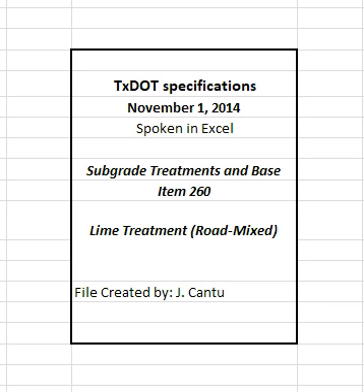2.2 Subgrade. The engineer will determine the sulfate content of the existing subgrade in accordance with TEX 145E and organic content in accordance with TEX 148E before lime treatment begins. Suspend operations when material to be treated has a sulfate content greater than 7000 ppm or an organic content greater than 1% and proceed as directed.